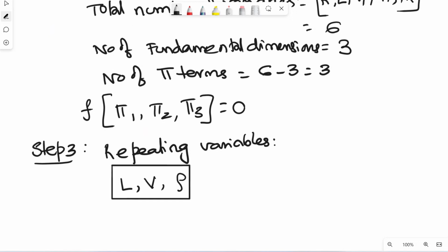So this is now one geometric property, one kinematic or flow property, and one fluid property. The fluid properties they have given are rho and mu. Out of these two, I have to choose only one. Now we select it. Of the three repeating variables, the first contains L, the second LT^-1, and the third ML^-3. All put together they contain mass, length, time, so there is no problem at all. No two repeating variables have the same dimensions.